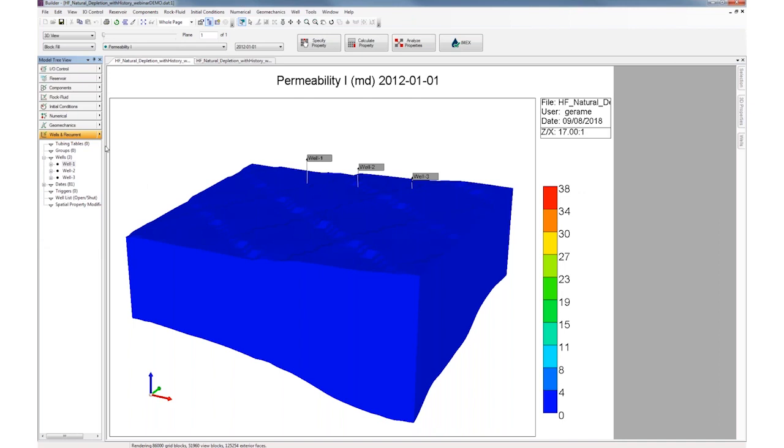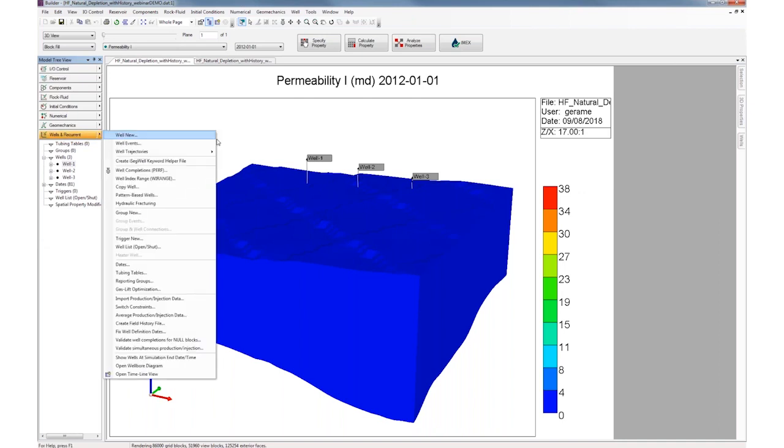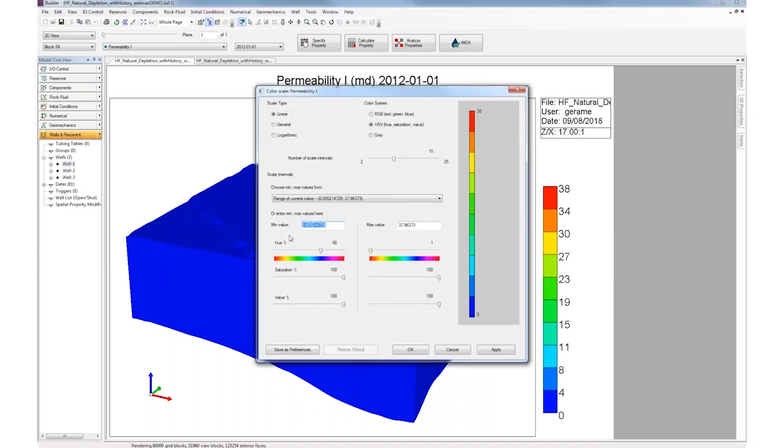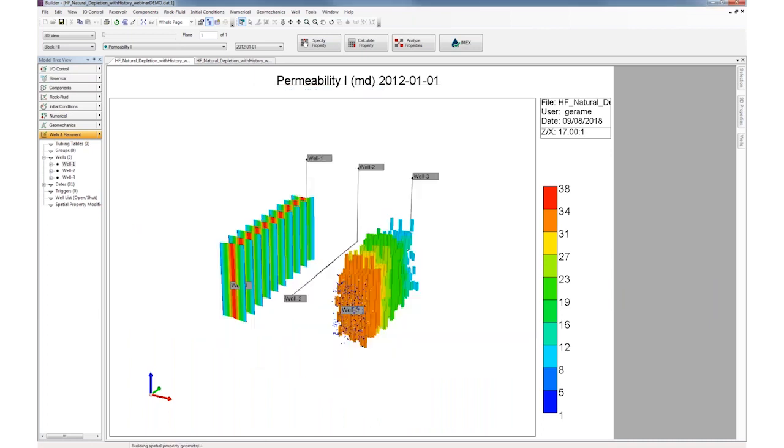All right. So I showed you how to do the planar fracture template there. The second option that we have would be to use data coming from a hydraulic fracture wizard. And what I'm doing here is I'm just manipulating the 3D view of my builder to take out any of the low permeability matrix blocks to show you exactly what we did in that step for well 1 there.